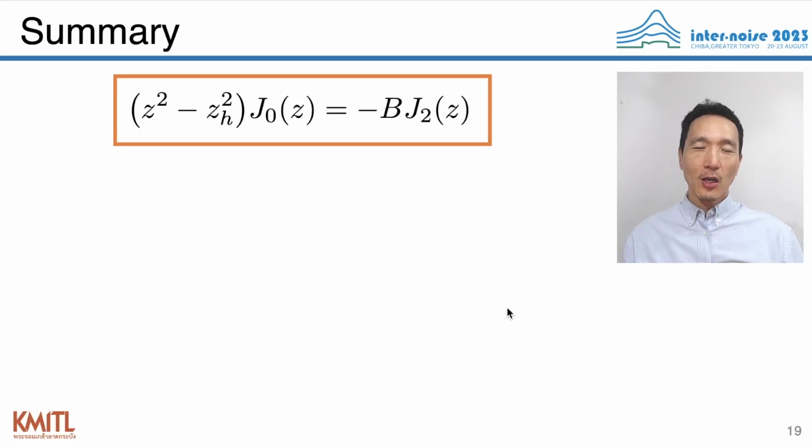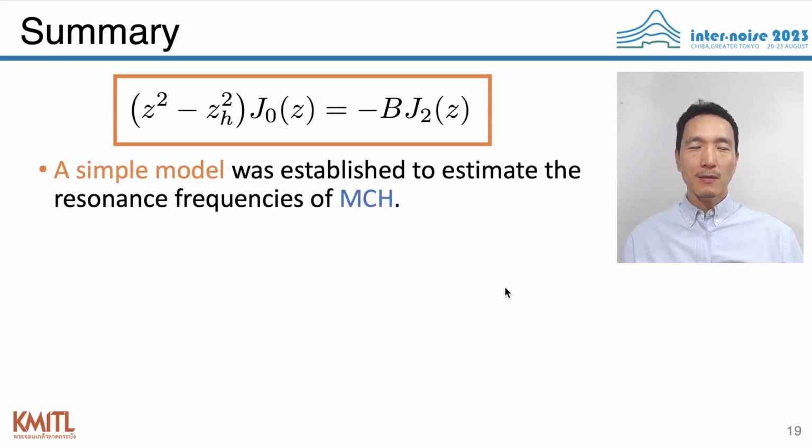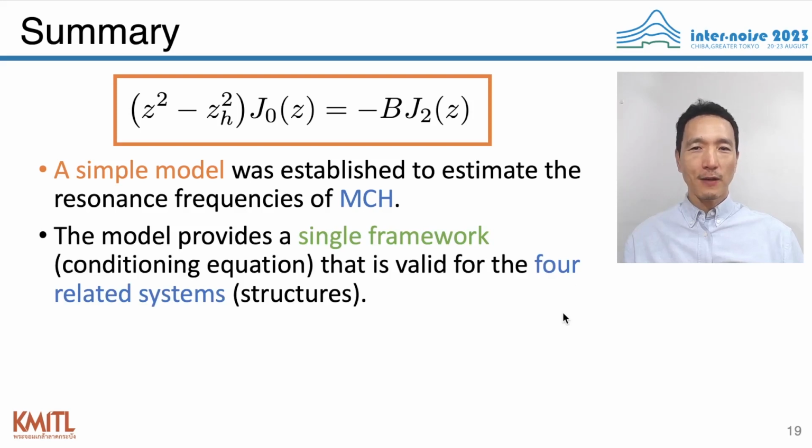So here is a summary of my talk. First, I propose a simple model which could estimate the resonance frequencies of the membrane-coupled Helmholtz resonator. The conditioning equation shown above in the orange box actually provides a unified framework for the modal analysis of the four related systems: hardware Helmholtz resonator, circular membrane, kettle drum, and the circular membrane coupled with Helmholtz resonator.